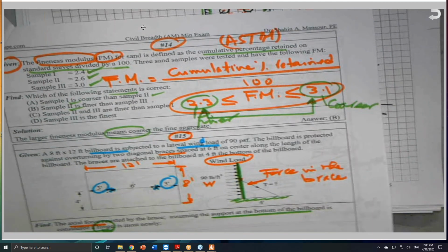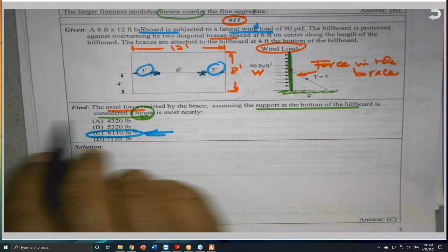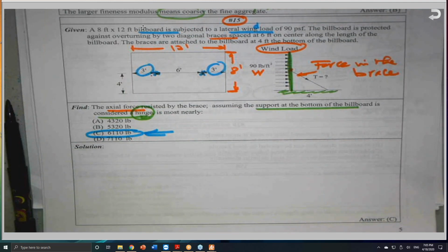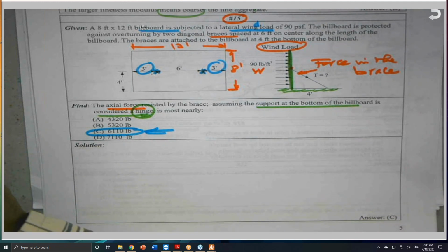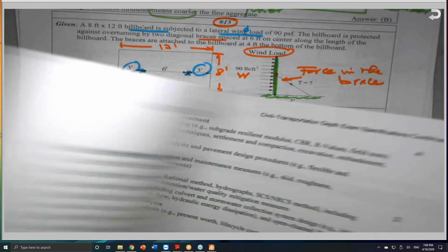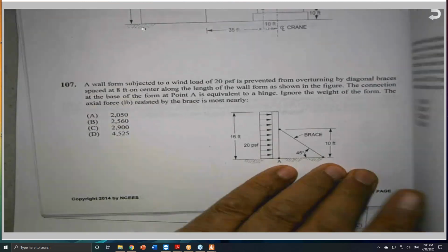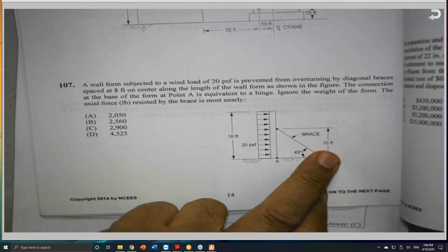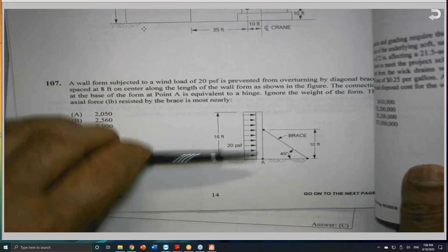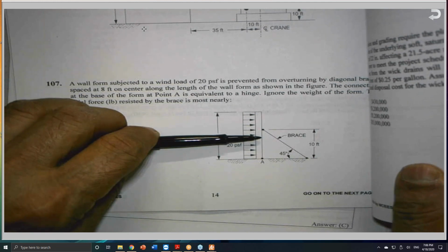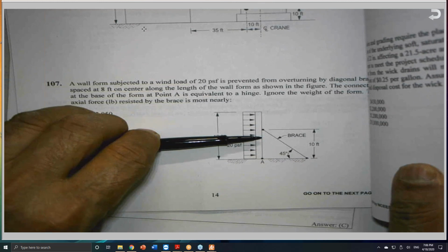Oh yeah. Again, one of you asked me about the Max. I told you that no, they don't. As far as the combined stresses, it is similar to the problem given in the NCEES book, and we dealt with it as an axial load only, without really combining, because the brace here is 10 and the load is going to be here, my friend. The load is also not aligned with it. The load is going to be 8 feet only, and 8 feet and this brace. So it is the same logic that I explained to you.